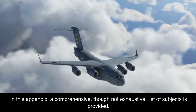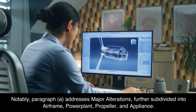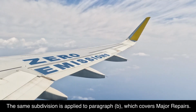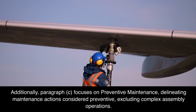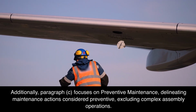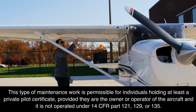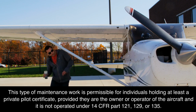In this appendix, a comprehensive, though not exhaustive, list of subjects is provided. Notably, paragraph A addresses major alterations, further subdivided into airframe, powerplant, propeller, and appliance. The same subdivision is applied to paragraph B, which covers major repairs. Additionally, paragraph C focuses on preventive maintenance, delineating maintenance actions considered preventive, excluding complex assembly operations. This type of maintenance work is permissible for individuals holding at least a private pilot certificate, provided they are the owner or operator of the aircraft and it is not operated under 14 CFR Part 121, 129, or 135.